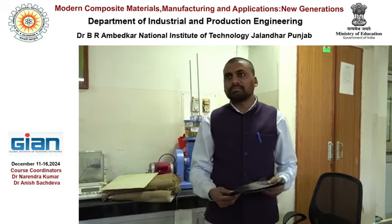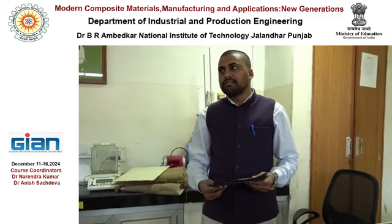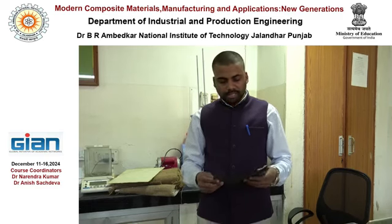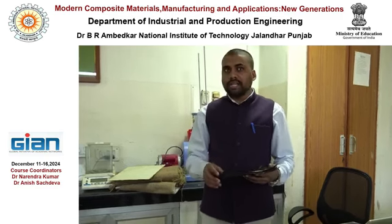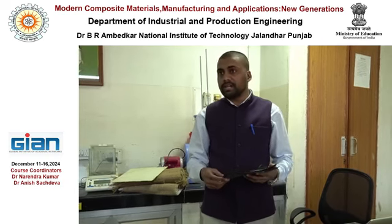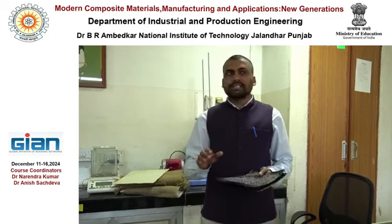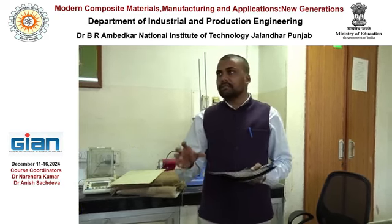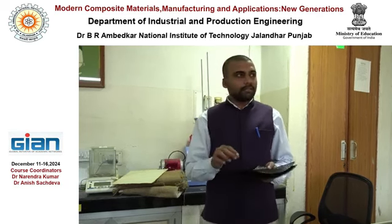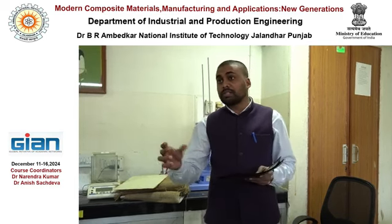So epoxy resin might be inflammable, it might burn? No, epoxy resin is not flammable. So you can cure it at a higher temperature also, for example at 120 degrees for around 20 minutes. Epoxy resins come in various grades depending upon the composite manufacturing technology, and it also depends upon the type of application.